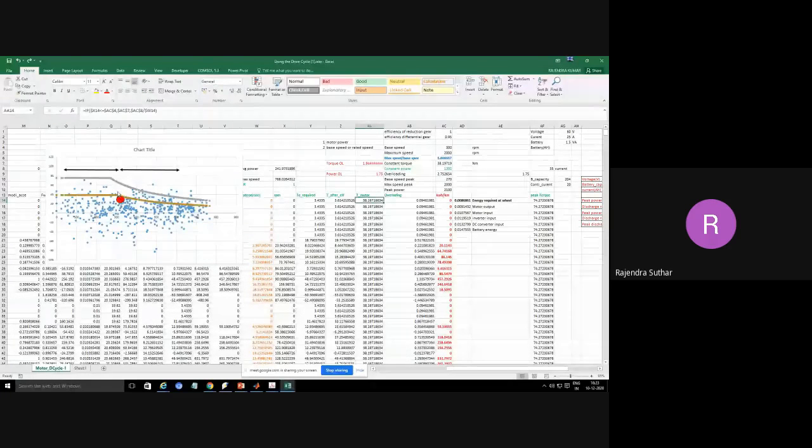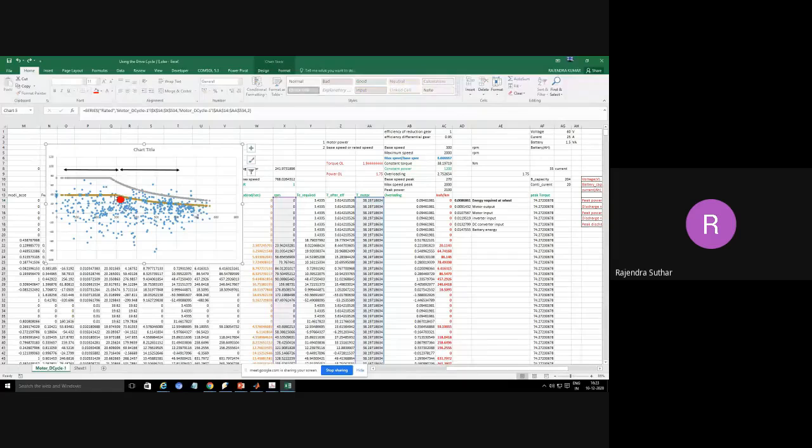And then what happens? Power remains constant, and torque starts to decrease. So power P is equal to T omega, that is equal to constant, and then torque is equal to power divided by omega. And which power is that? That is this maximum power where power becomes constant, which is called the rated power.